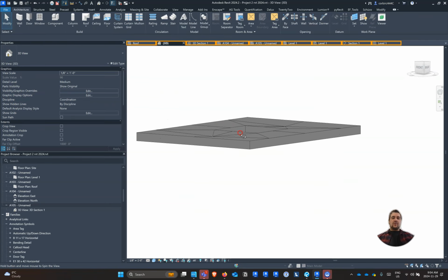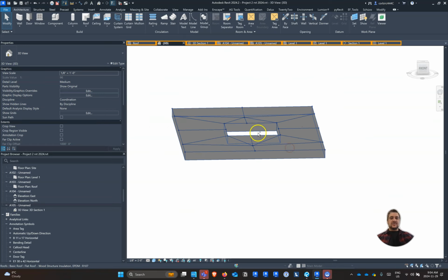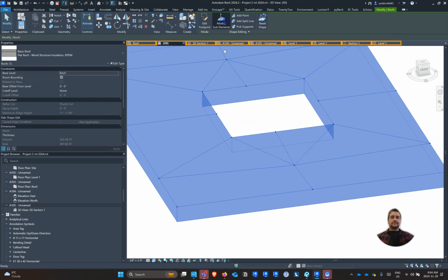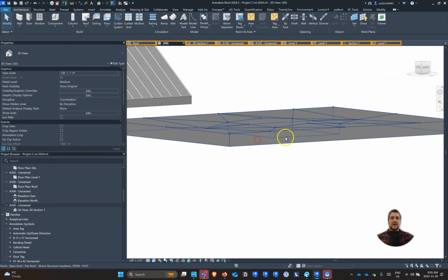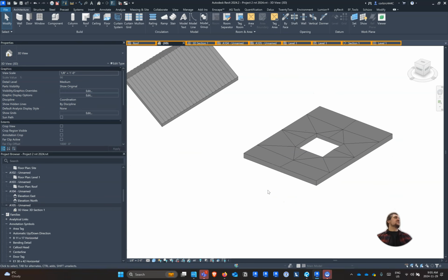So you don't have to do all those lines, but I find the lines are really helpful because they help you slope and know what's going on. The only other thing we probably should lower is these 3 points across here. And I'm just going to lower these -3, so they're sloping towards that point. So that's how you do flat roofs and slopes and things.